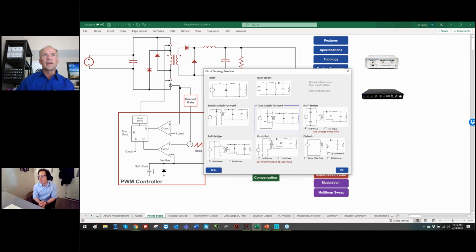Well, we do a lot of consulting out there, and I would say most of our consulting, believe it or not, is on flyback converters. People build a flyback converter from an app note or from Power Integrations or somewhere. They have trouble when they go into production, so we help there because everybody needs a bias supply. So in terms of the work we do, I'd say the flyback is number one. But in terms of number of converters built, the buck converter is number one in the world because every point of load power converter has a buck converter. Shifting a little bit these days to resonant, isolated converters, but still the buck converter is predominant.